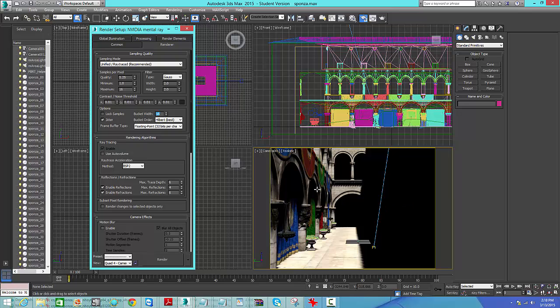so it actually reduces your own personal time sitting there waiting for a result, as opposed to the entire time for the scene to render, because that's absolute. You're always going to have the same amount of time to render the scene overall, but if you're doing test renders, you want it to be as quick as possible. So having a smaller bucket size allows you to see a result faster.